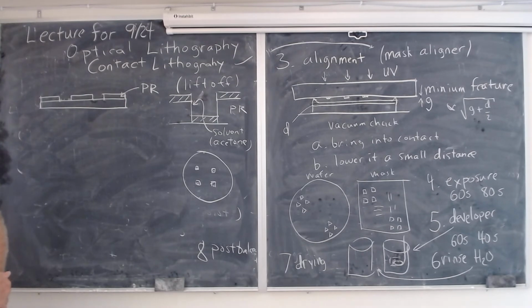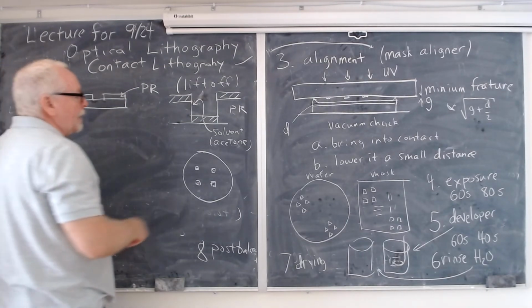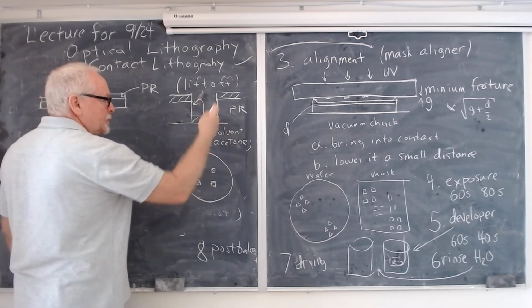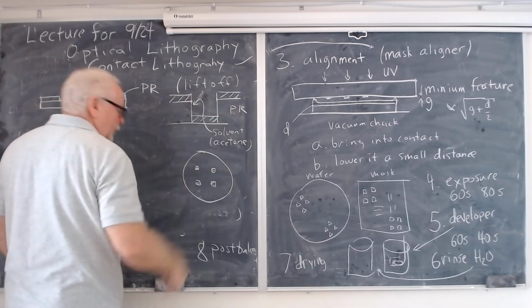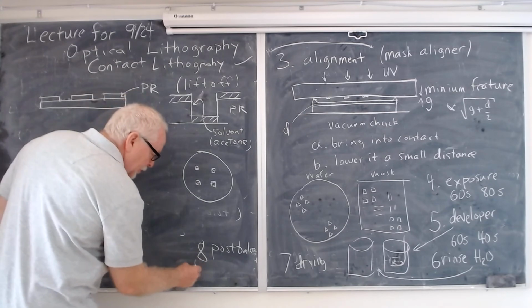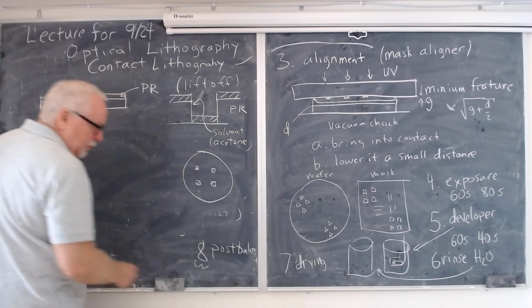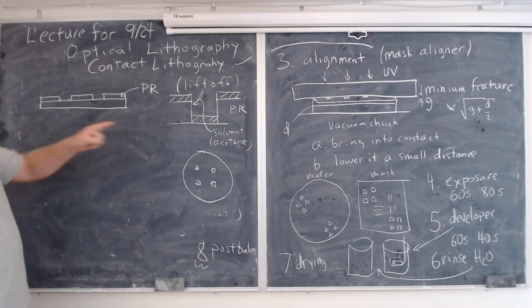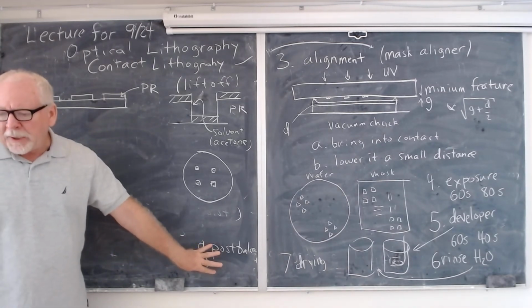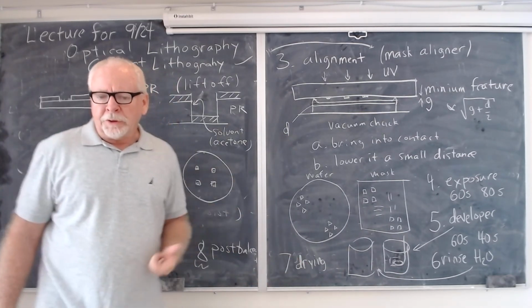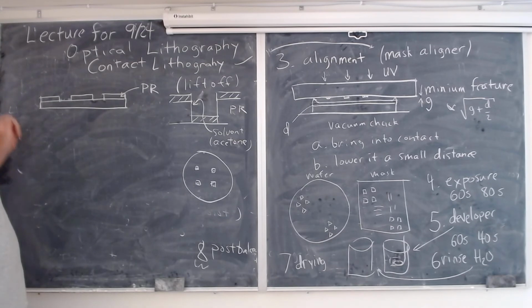Rarely does it work that well. In fact, what usually happens is that you have to agitate, like with an ultrasound, in order to get that photoresist to dissolve. But anyway, getting back to step 8 here. I'll put wavy lines under it because it's optional. If you're doing liftoff, you don't do step 8. Once you dry the sample, you put it in the evaporator and you do your deposition.